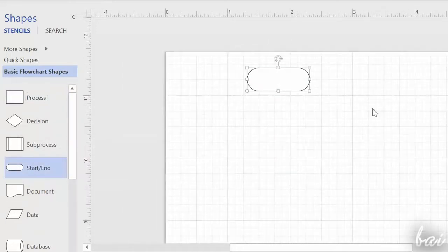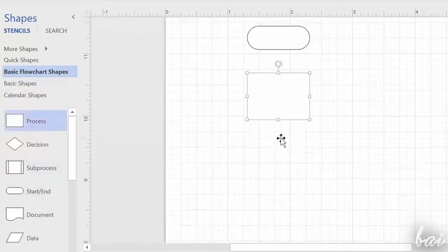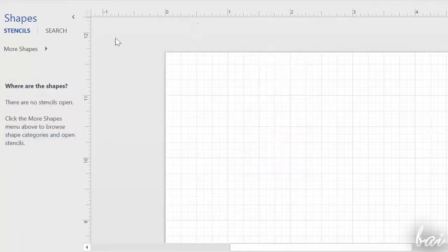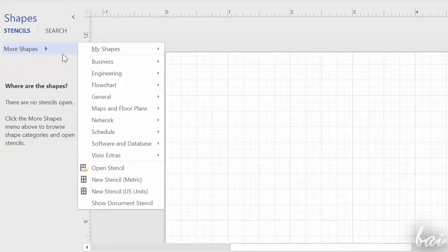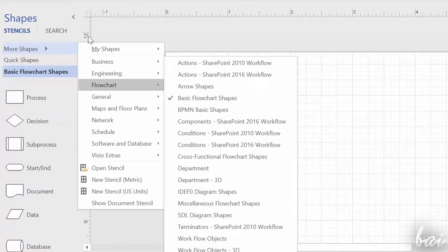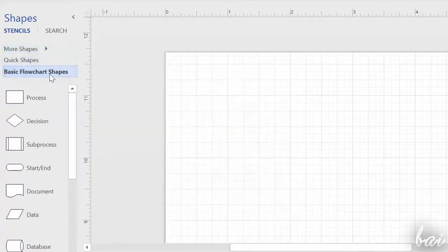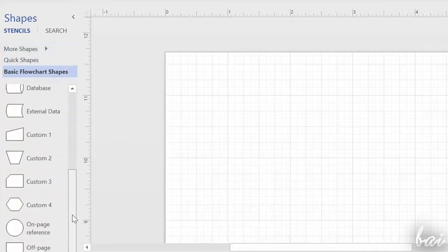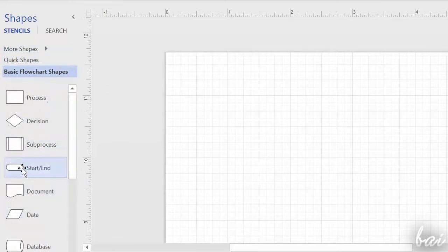When you start drawing, it is always better to start from the shapes. On the far left, you have the Shapes panel that collects all the different shapes available inside Visio by default, all collected inside different sections called stencils. Choose the topic you are interested in and find the right shape, and then simply click and drag this on your page to import a copy.